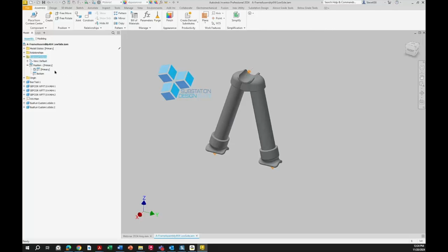So I can have different positions of these items. So if I come over in here at my position representation, I'll hit bottom, and you can see now it's at the bottom. So my bus tool just came to the bottom. Now I'm going to come up here. So what's going on behind the scenes? We'll open up the bus tool, and you can see the mates turning on and off here. So I'll come into the bottom. These mates are enabled, and these mates are suppressed. Come to the top, and it's the other way around. Okay, so that's what's happening.